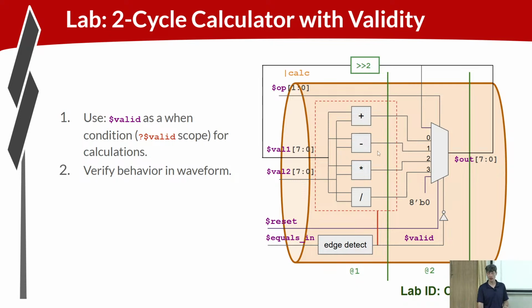Therefore, for clock gating, for example, there's no reason to provide the clocks for the flip-flops that are carrying the result of this computation through to the mux. And there's no reason for us to look at the values in the waveform. We should know that we're not using them.